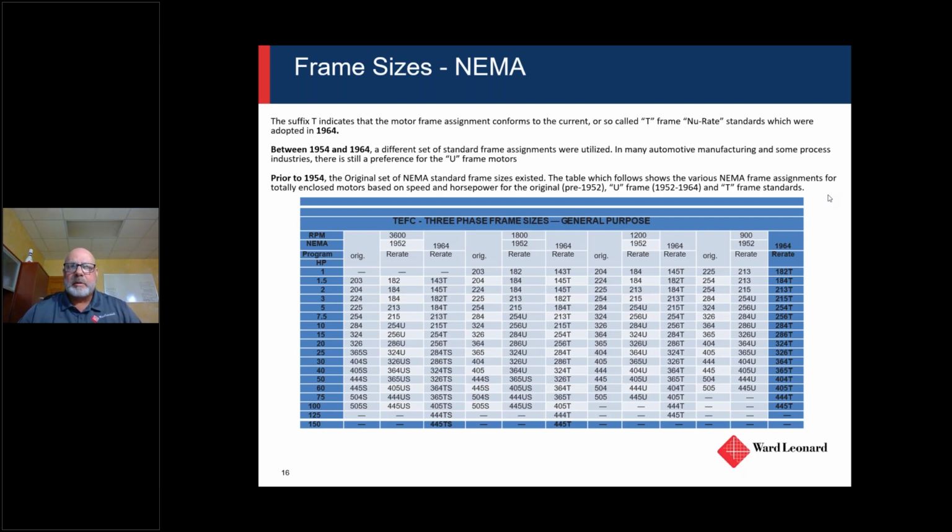But that was really part of the reason why those motors were so big, just because they had to have the large motor for airflow into it and for the ability to wick heat away. Those types of things, just overbuilt, very much overbuilt. So you can see the difference in designs. So when it was a 1952 NEMA or U-frame motor, dimensionally, the newer motors are much, much smaller, right? Much same horsepower, same torque in a smaller package.